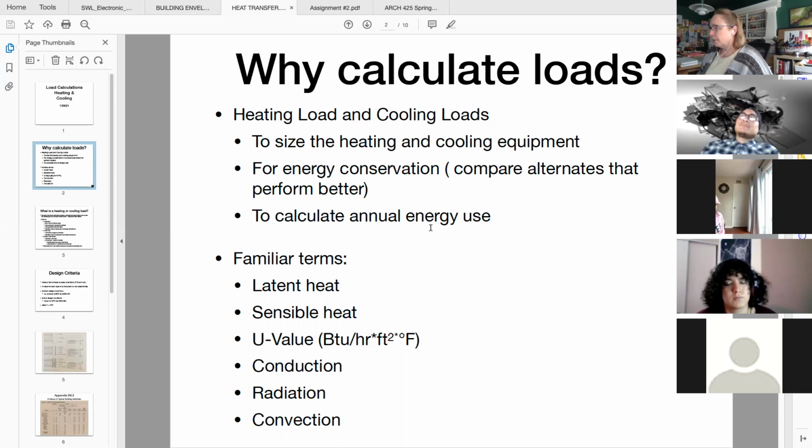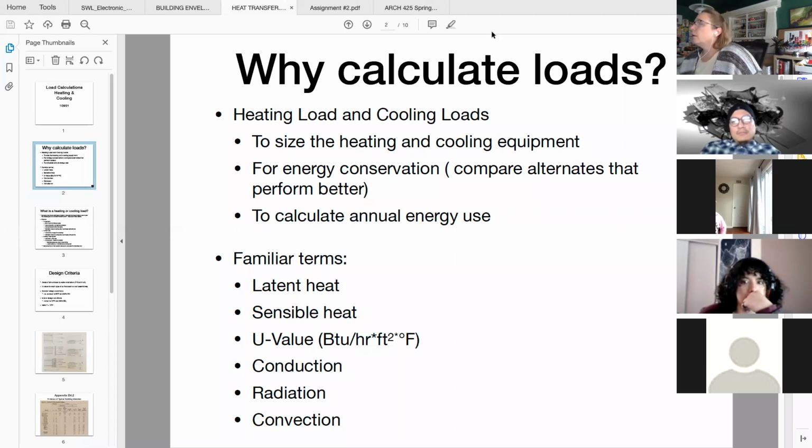And there's one other factor. If there's a large humidity difference between the exterior and the interior, when you're looking at your ventilation, which is bringing in your fresh air, if it's much more humid on the exterior, when that ventilation air comes in, it could be adding humidity into your space, which is adding to your load. Now, there's a lot of equipment out there these days that can help prevent that additional load coming into your space. And we will briefly touch on those when we get to our active conditioning mechanical systems.